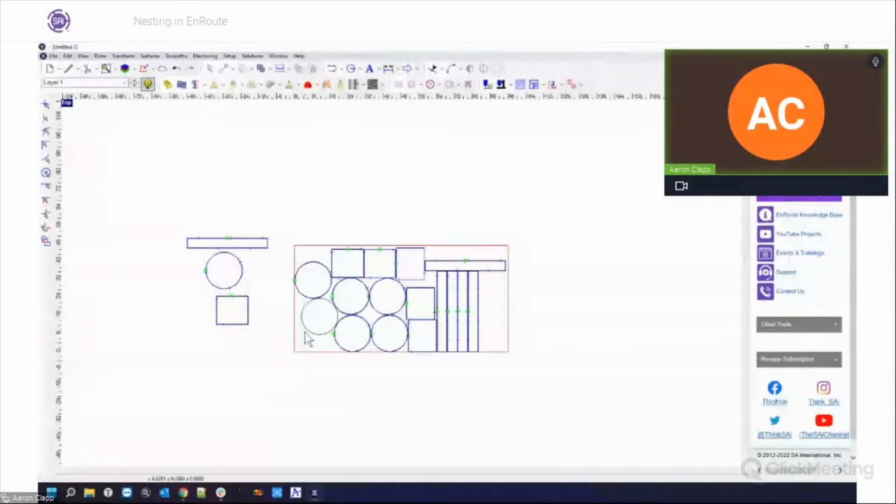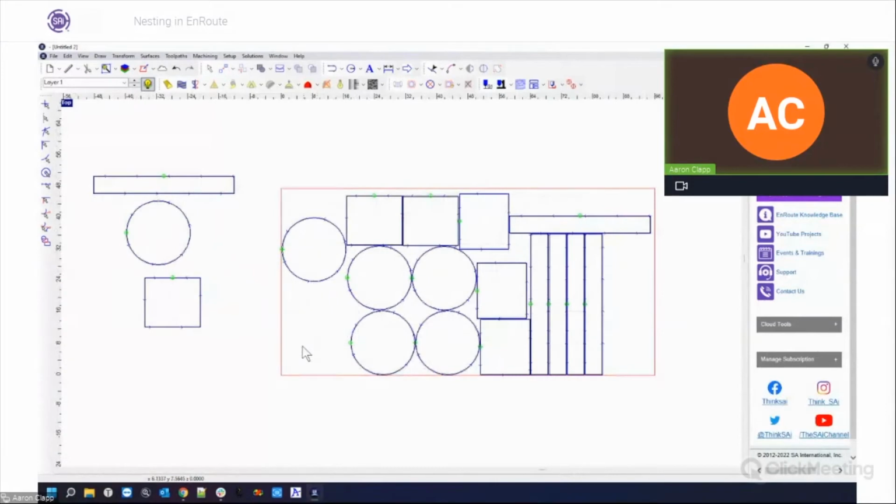So here was my obstruction, and you can see that it nested around it. It completely avoided this area of the sheet. So I could do that with any part, anywhere. I could line up all the places where the knots are and just exclude them from the job completely. Or if I have a piece of damaged sheet on this side, or if there's something going on in the middle, a cluster of knots or damage on the material, but you still don't want to throw it away, you can get around that by using the obstruct feature in the nesting options.